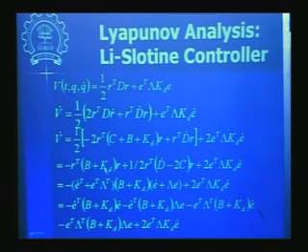Now we know that this r transpose (d dot minus 2c) r is equal to 0 because of the skew symmetry property of this matrix that we have seen in the earlier classes. This d dot minus 2c is skew symmetric, so a quadratic form with a skew symmetric matrix will be 0. If you evaluate that form, it will be 0. So we use that property here.